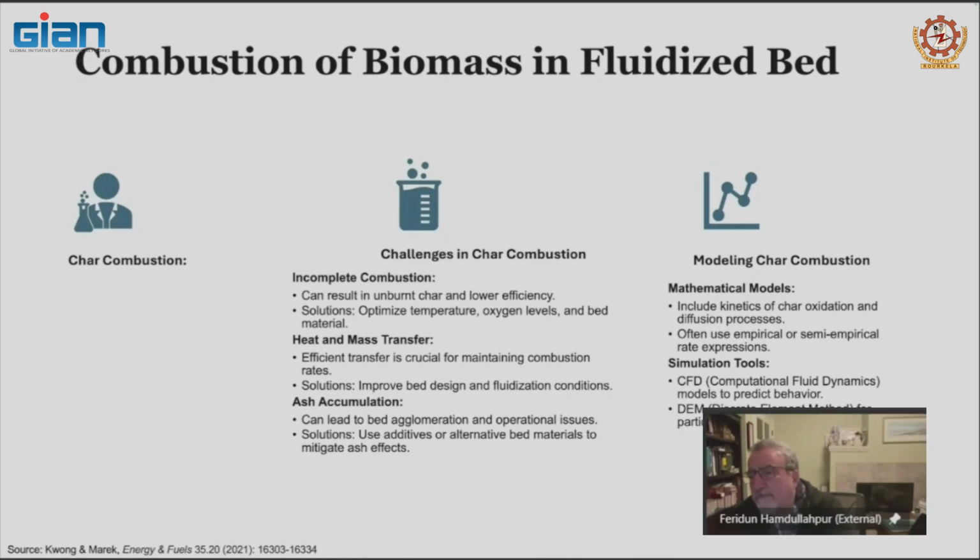You adjust the batch size accordingly to make sure that you have enough time to dry the fuel that goes in. For example, you can partition the bed, and as the fuel dries, it weighs less and goes over the partition into the combustion chamber.